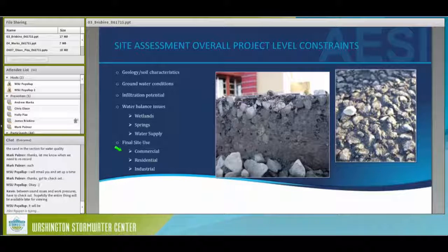And there's a couple of photos here that really illustrate a good point. Mark, the previous speaker, had a photo of a porous pavement that somebody seal coated on their driveway, which effectively negated any infiltration through the pavement. This is a project we were involved with some years back with a Red Robin restaurant, and they had a porous pavement, but it stopped infiltrating.